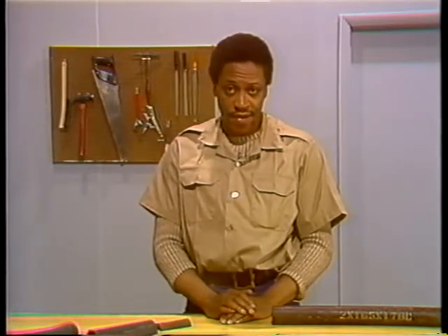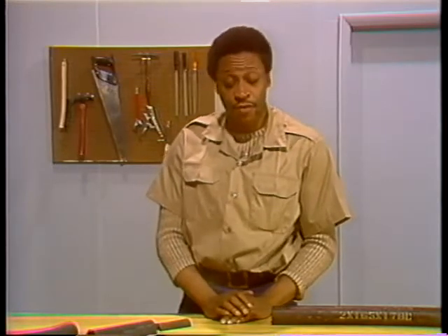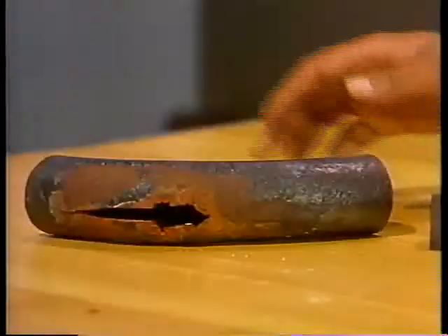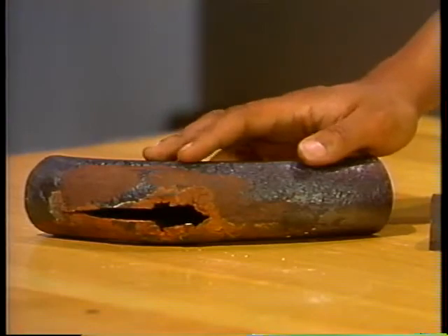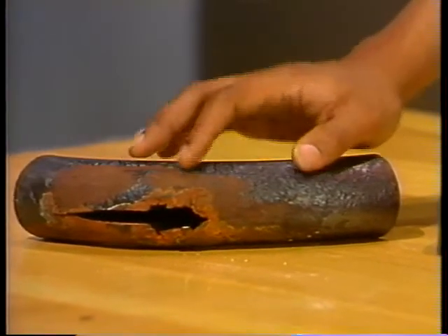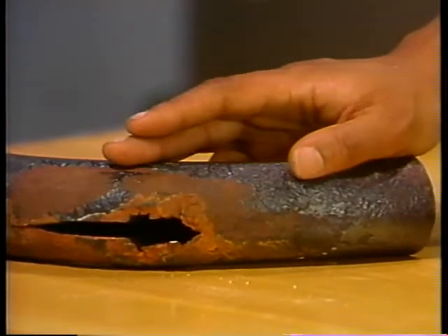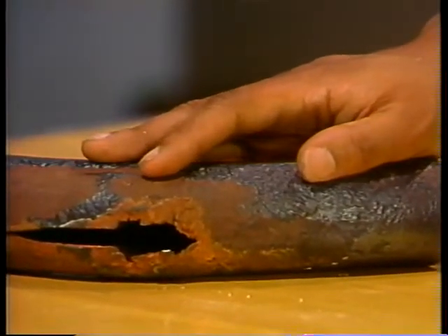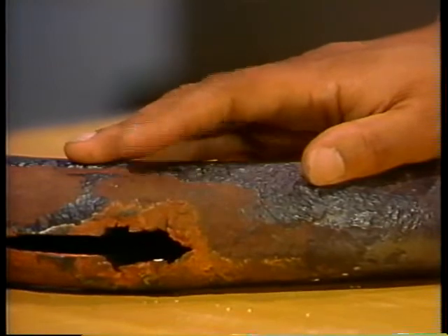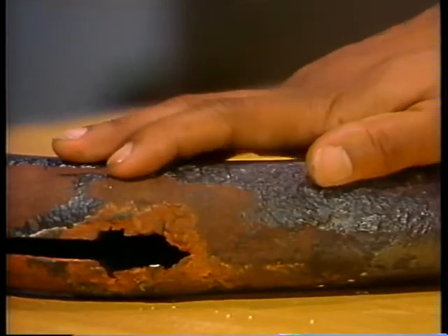Another way corrosion can happen is by leaving a boiler open and wet during shutdown. This will lead to rust, which is a form of corrosion. Corrosion can also be a problem on the outside of the tube. Here, corrosion is the result of moisture combining with the sulfur found in ash or soot. This produces acid, which attacks the tube metal and corrodes it.